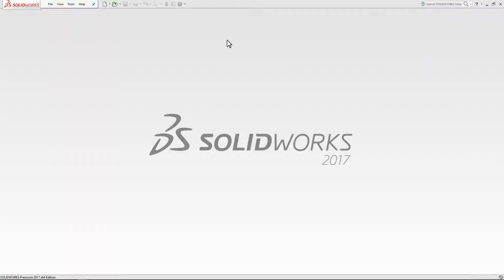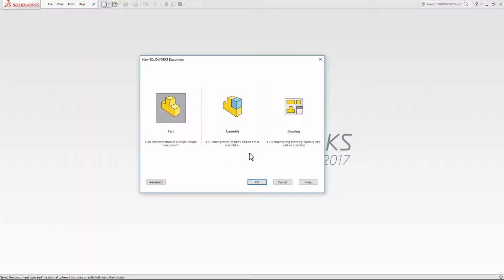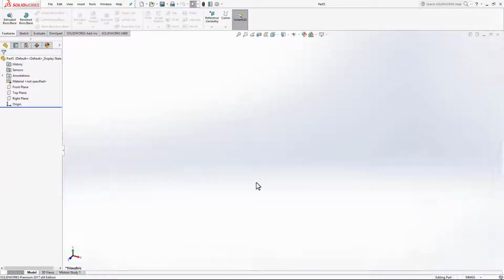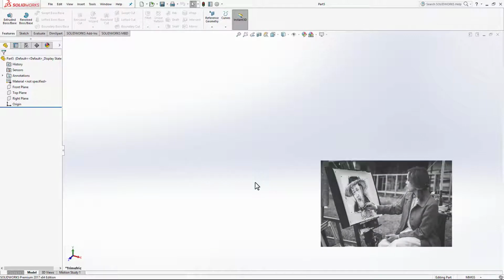When you launch Solidworks, go to File and click on the New icon. In this window, choose Part and then click on the OK button. Now you are in the Part Editing environment. To create and then edit a part in SolidWorks, we need to draw its base sketch first. Every 3D model in this software is based on a sketch, and just like the way it works in the real world with pen and paper, every sketch needs to be drawn on a plane too.